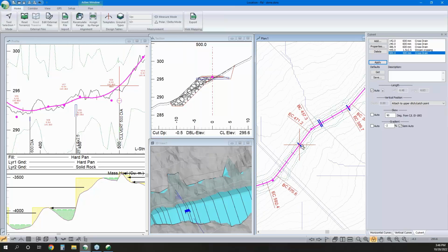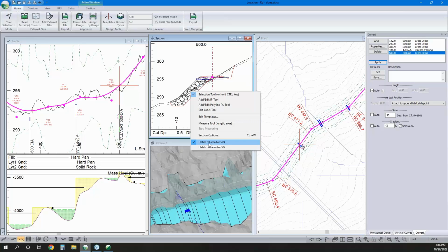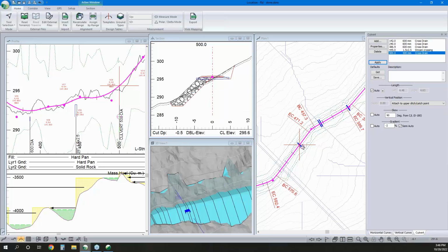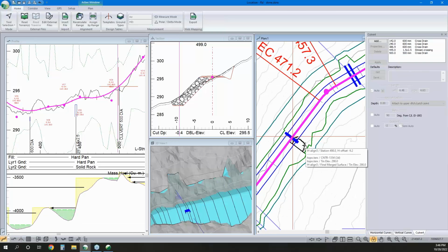And we can right click in our cross sections to see what different layers are being tracked as. So I've done that previously. I knew this is being tracked as surface volume 4, so that's why I shaded surface 4. I feel like you knew the next question, and maybe you took a peek at the question panel, which was the next one, which is how do you know which layers are in your template? You added a lot of layers in your reference corridor services.